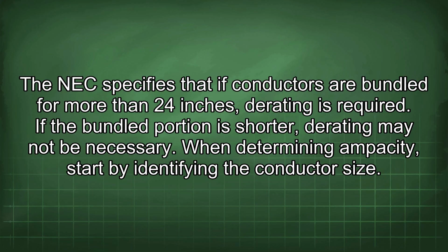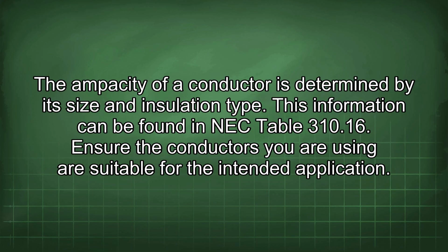When determining ampacity, start by identifying the conductor size. The ampacity of a conductor is determined by its size and insulation type. This information can be found in NEC Table 310.16. Ensure the conductors you are using are suitable for the intended application.